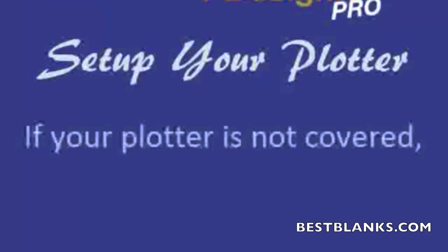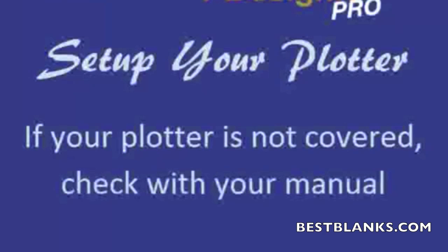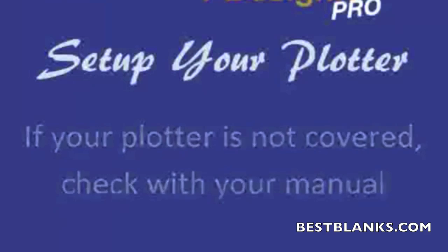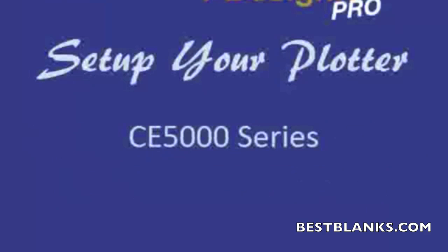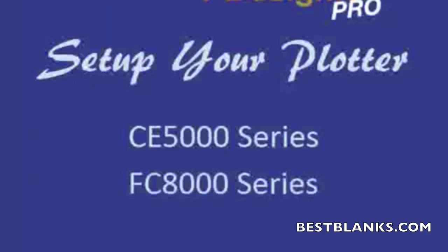Well, the next thing we want to do is set up your Graphtec plotter to make sure that the settings are compatible with its software driver. Each cutter or plotter has a different setup, so if your plotter is not covered here in this video, please check with your Graphtec Cutting Pro manual. We will first cover the CE5000 series, including the Graphtec Pro, and then we'll cover the FC8000.